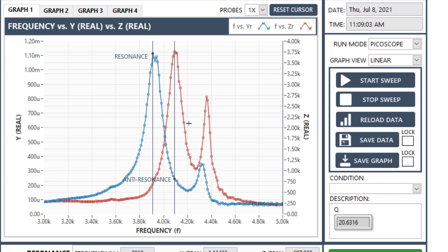So this clearly would enable you to, if you remember what the impedance plot looked like, I'll show it again in a second, you wouldn't be able to pick out your resonance and anti-resonance frequencies, but here you can clearly tell that there's a mode there, there's a mode there, and again now there's a mode here. This is the resonant mode of this frequency.